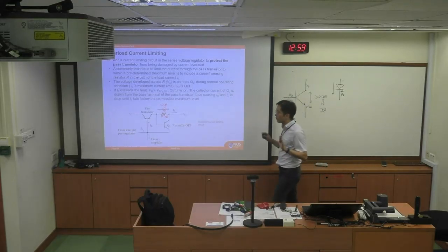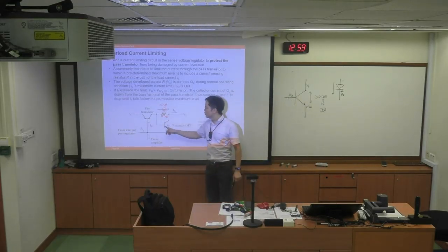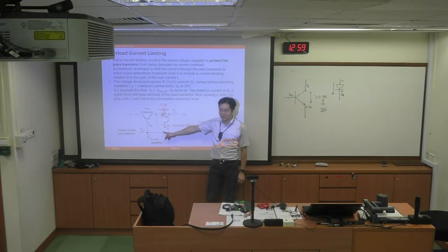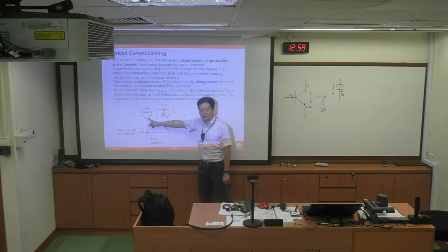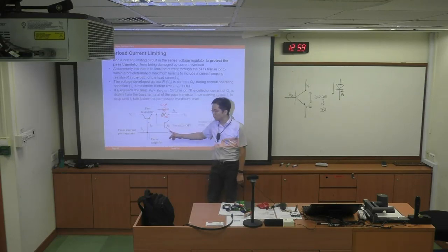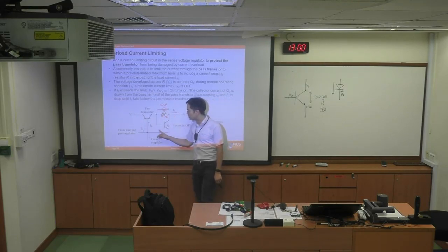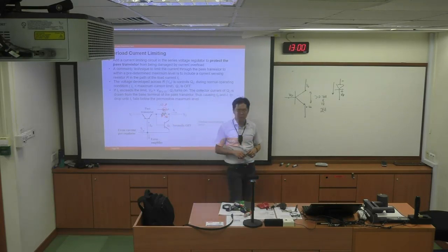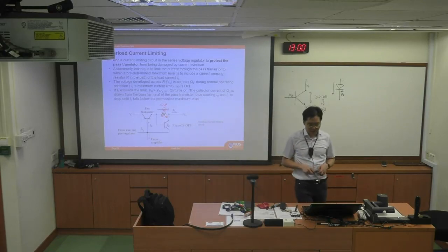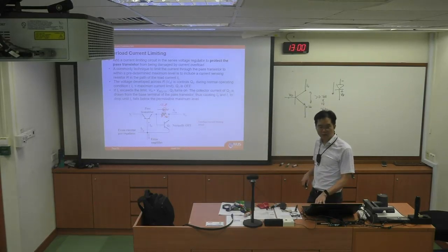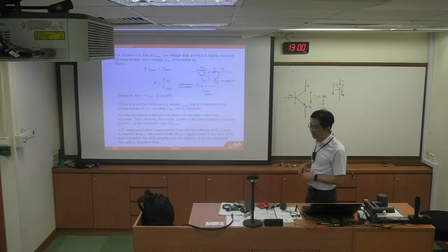Okay, so to summarize up to this point, these two look the same in the schematic, but actually this is a power transistor that potentially can flow tens of amps, whereas this Q2 only flows several milliamp of current, so that it can actually shunt away excessive base current to the power BJT. Any questions up to here? Let's take a careful analysis here.